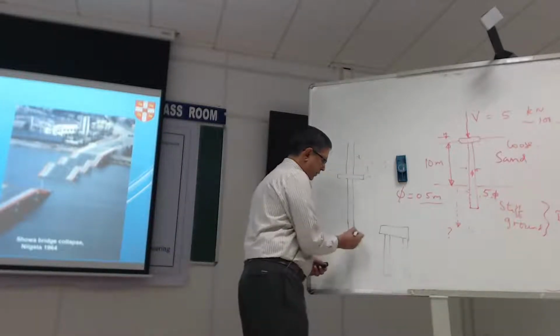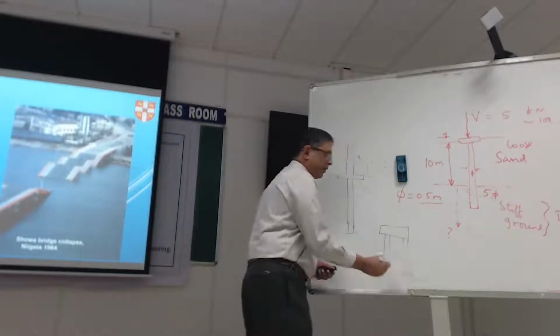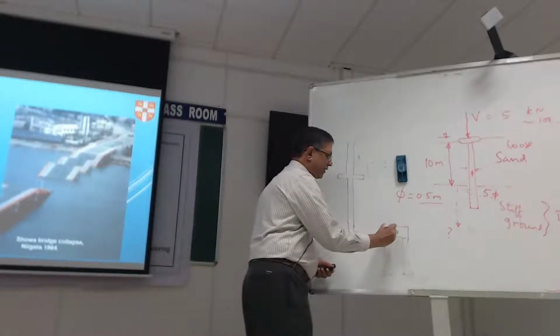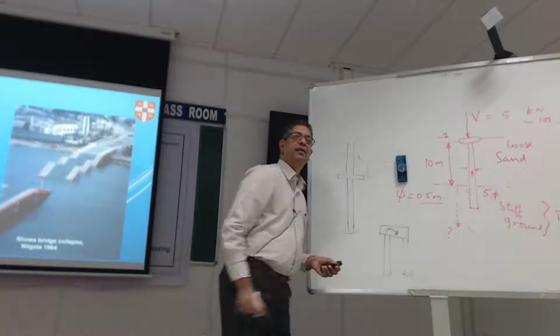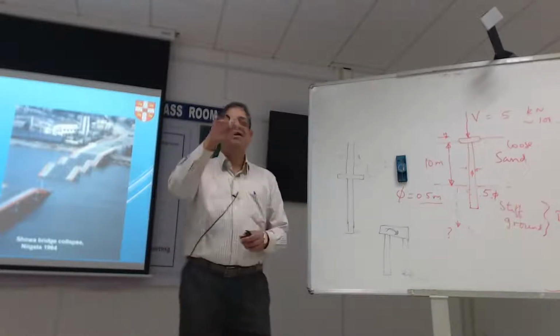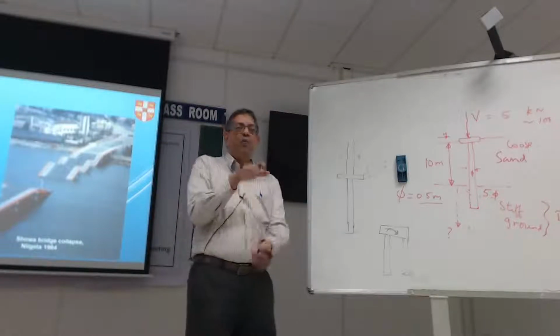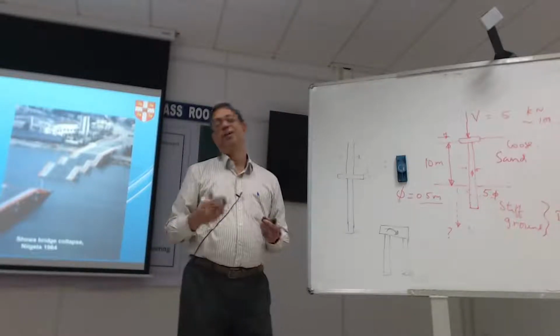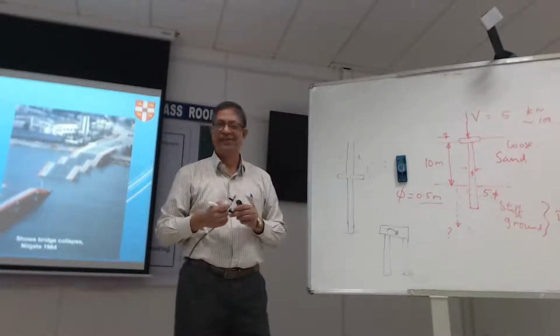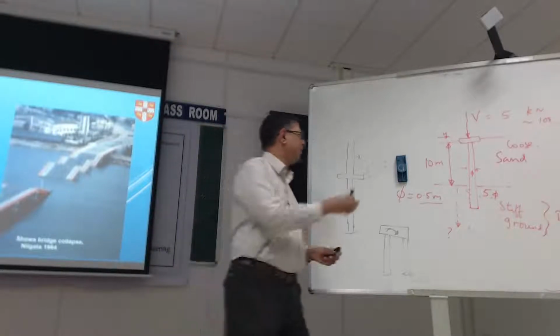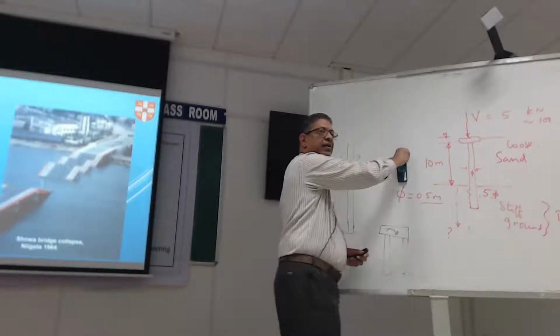This way, you will have more rotational stiffness. Just because the decks are trying to go backward and forward, it's never a good idea to have one row of piles. But this is 1964 design, so we'll cut them some slack.